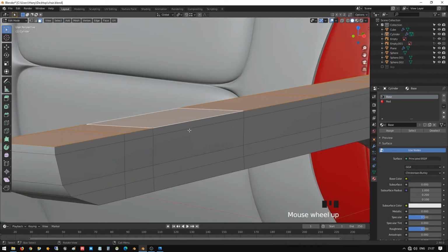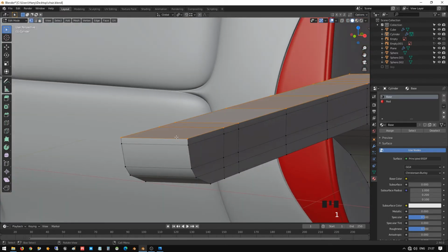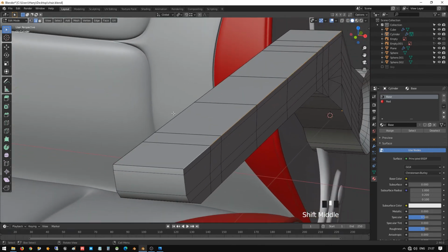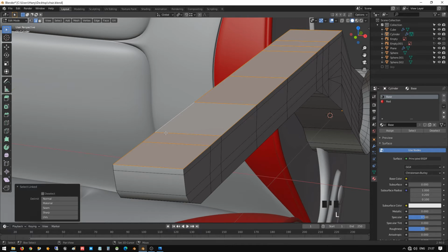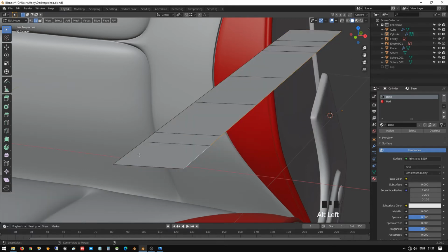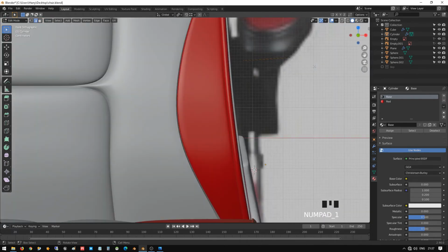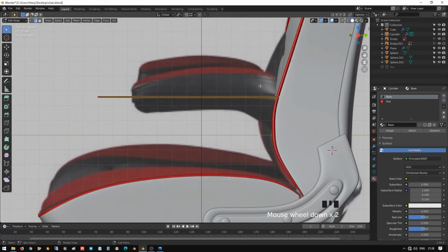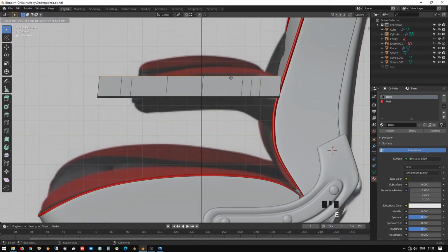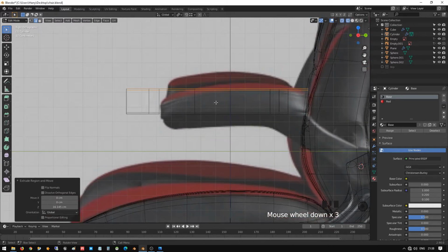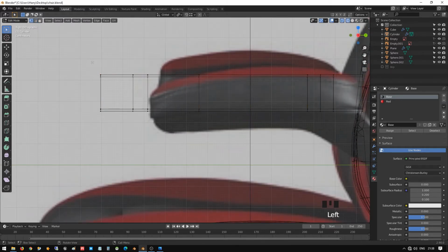Okay, set in solid mode and go to its selection, it's selected. So the Alt H. Okay, go to edge selection, go to front view, sorry, right view, and extrude in this angle. Okay, and Shift Z, go to wireframe mode and select this one.